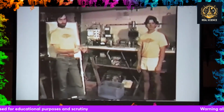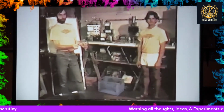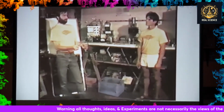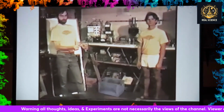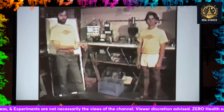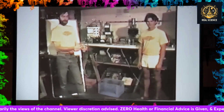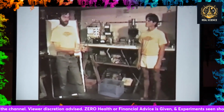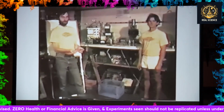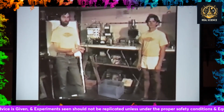So if anyone wants to take the effort with the length, the gauge of wire, and temperature rise over a period of about how long would you say? Oh, 10 seconds. 15. So that would give the inquiring member of the audience that wants to perform the calculations the amount of energy this device produced. For 10 gauge to get noticeably warm that fast, the current would roughly be 100 amps.